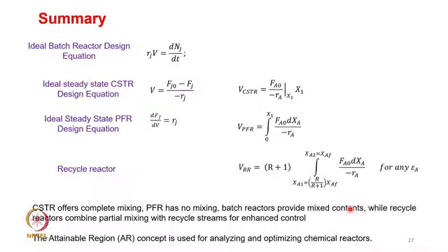Okay, so I think these are the key concepts in geometric design of reactors. Maybe we will just summarize whatever we have learned till now. We have learned about basic reactor balance, then the ideal batch reactor design equation, the ideal CSTR design equation, the ideal PFR design equation, and eventually a recycle reactor design equation. In all of these, you will be able to find out the corresponding volume by manipulating the variables.